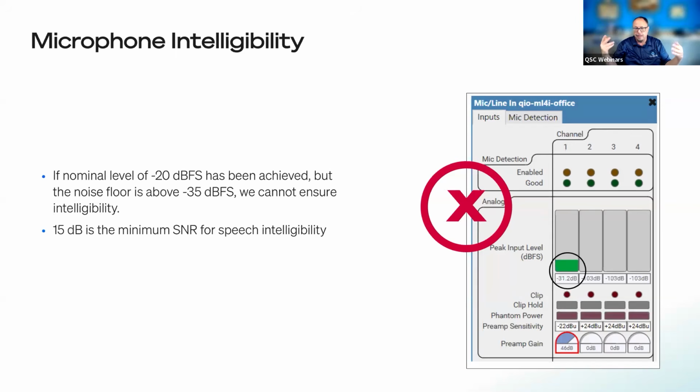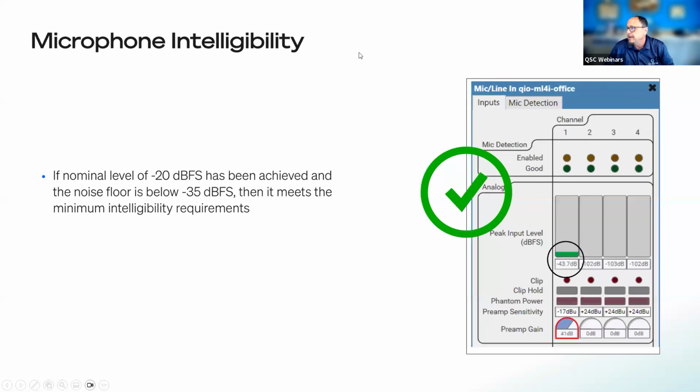then you're going to have to adjust something in the room. If you increase the preamp gain to make the microphone signal louder, you're also increasing the noise floor just as much, so that's not helping. So you have to address that at the source if you have issues with that. And the source could be noises in the room, acoustic treatment, whatever those are. I know those are hard conversations, but sometimes you just got to know that you have to address it that way.